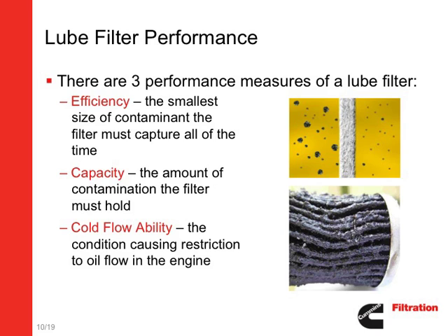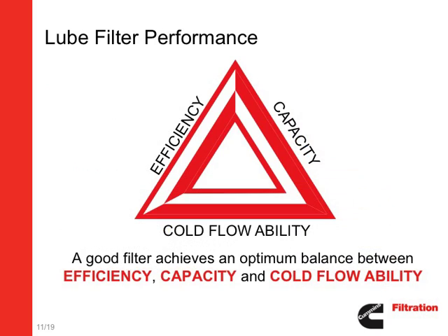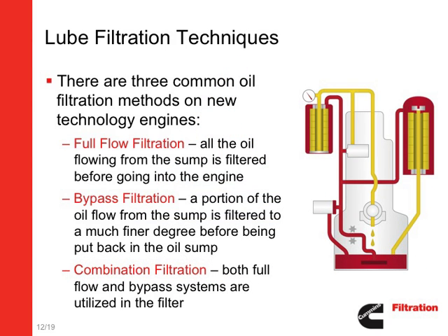Higher oil flow restriction results in delayed oil flow to critical engine components, causing increased engine wear. A good lube oil filter achieves an optimum balance between efficiency, capacity, and cold flow ability. If a filter doesn't perform well for all three measures, it will not adequately protect your engine. In many engine applications, and especially severe service vocations, more than one lube filtration technique must be used to remove all of the harmful contaminants.